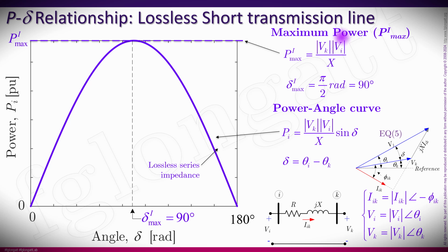So as you can see from the maximum power transfer, the number in the numerator is not so flexible because we have only 2% or 1% or up to 10% to modify the voltage. So to define a higher maximum power transfer, what we can do is affect the denominator of that equation.